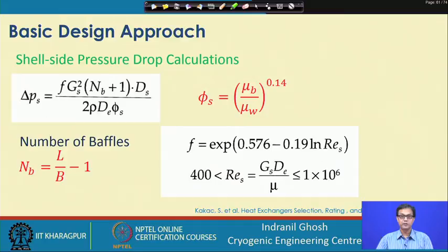So, there you will find that for accommodating 117 tubes, which is the number of tubes we have estimated, we have to get a guideline from TEMA, and obviously, you will find that the exact number of 117 tubes will not be available. So, the nearest possible number of tubes is close to 117, but it should be more than 117.